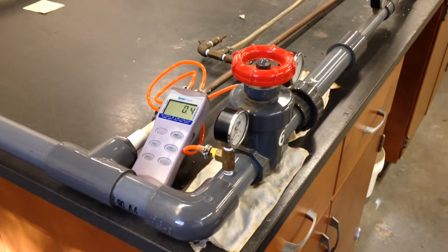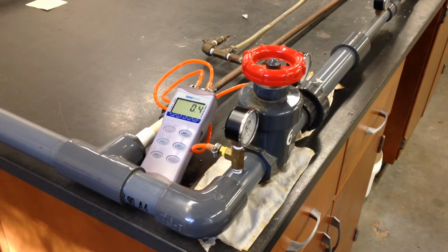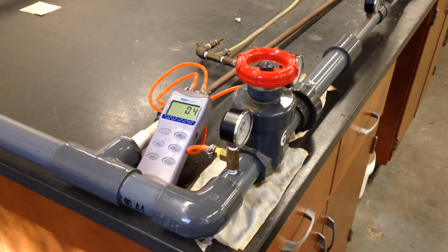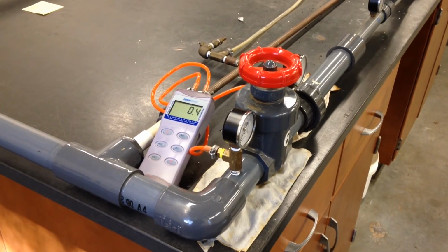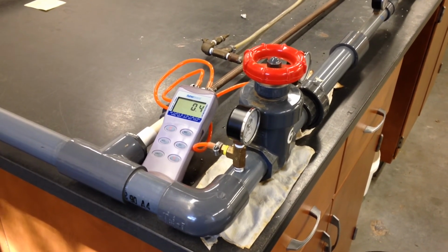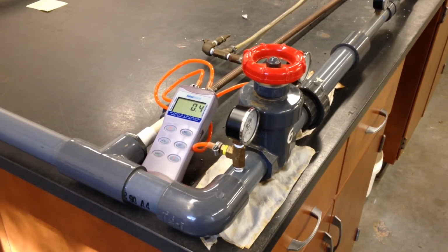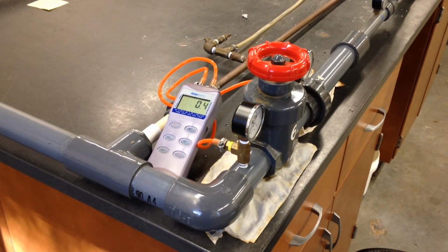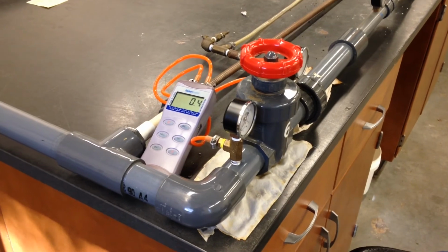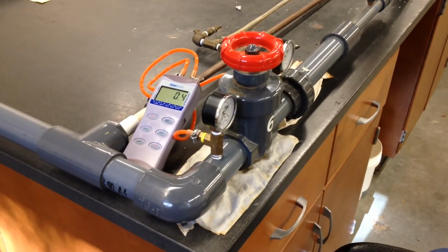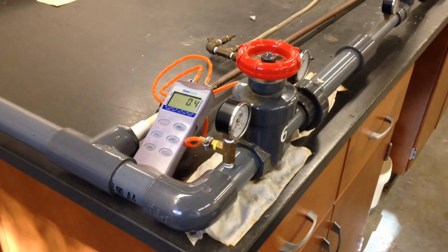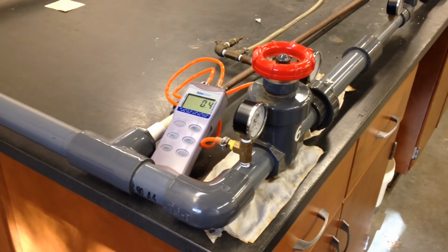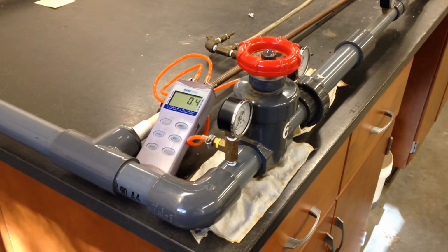We'll actually do a series of videos where we start with a flow, and you'll measure the digital manometer, and you'll go up for the full open. Then we'll turn around and do it for the 3/4 open. Then we'll do it for the half open. And then we'll do it again for the 1/4 open. We'll have different flow rates and head drops across the gate valve, and from those you compute K.